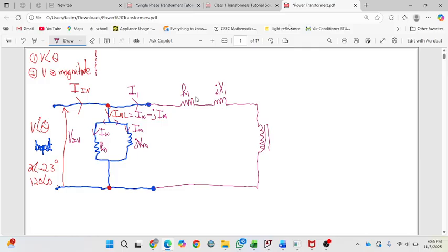The coil has a million and one turns, and when you pass current through that, you have heating losses. And this jX1 comes from the fact that you have a coil, well actually two coils, and they have a magnetic field that is generated. Some of these magnetic field lines don't cut the other coil fully. If it's not cutting it, it's not doing anything, so you're losing potential energy due to those losses. That is modeled by this X1.